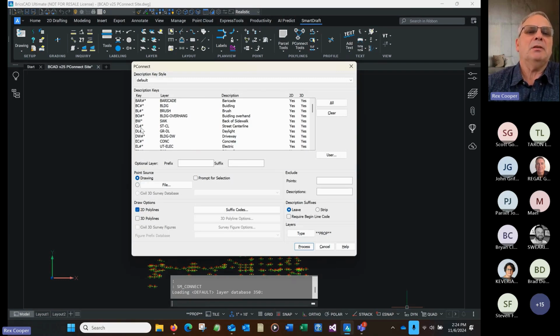And if it has this $ sign, it means that it can have a string that is like a top of curb, TC1, TC2, TC3, and you can keep doing cross sections and have multiple TCs, and they don't get mixed up with each other. Until you terminate it, it just continues to believe it's the same thing. And you could do the cross-section method, and you don't have to walk down a street and walk back up a street. You can mix and match as you go down and do a street, even if it has islands and whatnot.